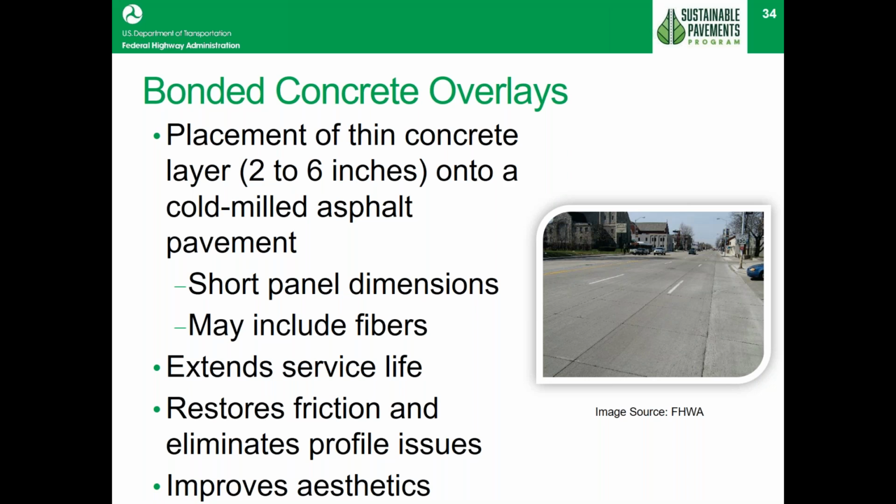Another typical use that has been done with them is as bus stops, because where buses stop and sit, they tend to drip oils and things like that tend to be very deleterious to asphalt surfaces. The process is really not too difficult. You mill the surface, you put down this concrete layer, you cut it into some joints, about a 4x4 joint or so, something of that nature.